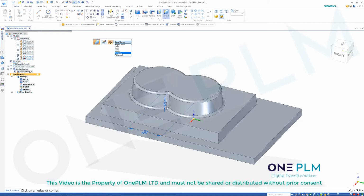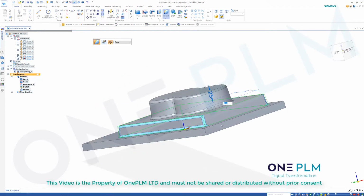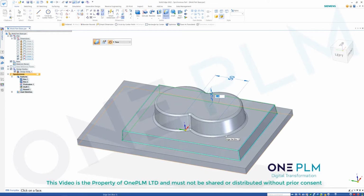We can also do stuff such as face as well. So if I choose face and select these faces, 1, 2, 3, 4, I'll do a 1mm round on those.